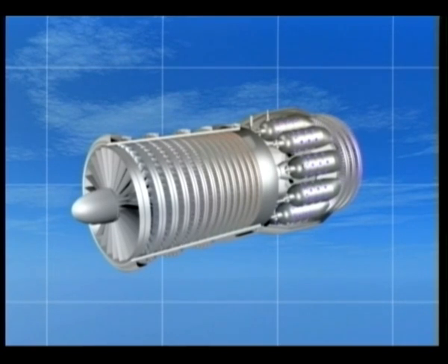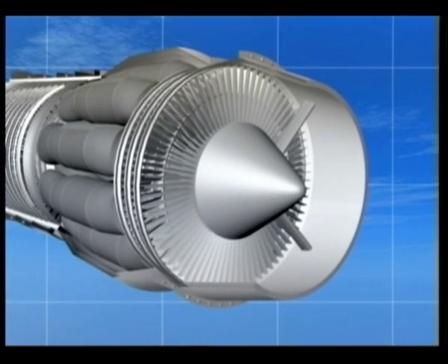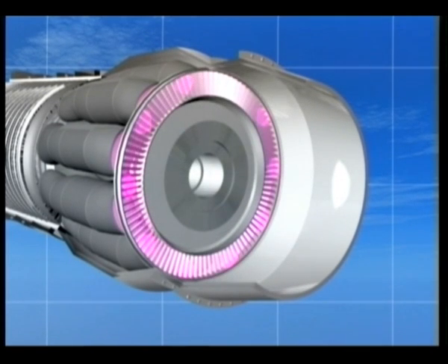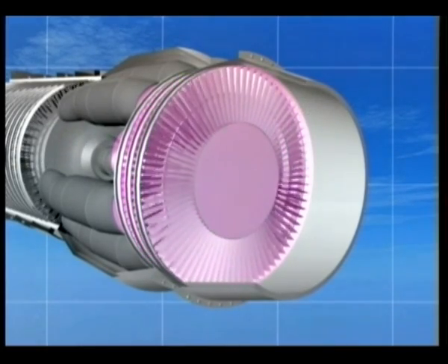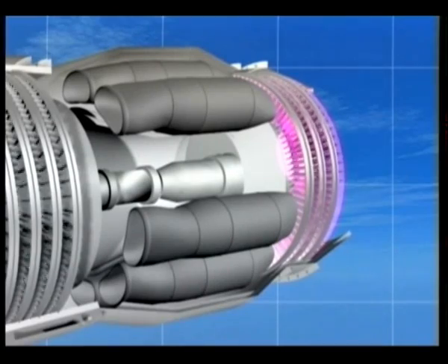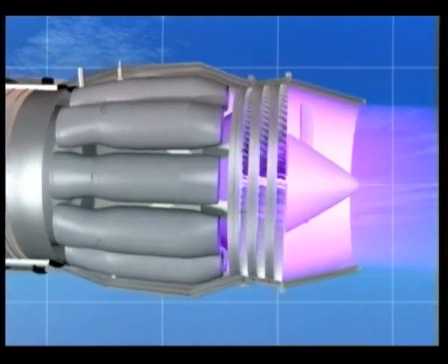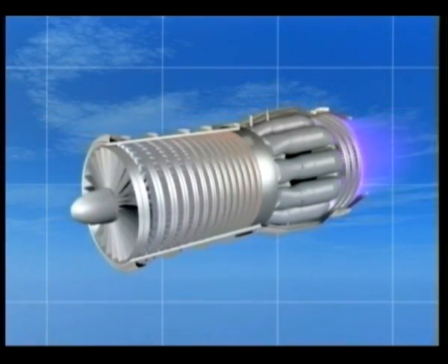the turbine. For a continuous flow process, if the flow is led through a convergent passage, the velocity must increase and there will be a drop in static pressure, density and temperature. This is the expansion process. The turbine disc carries the turbine blades and transfers their rotational force to the turbine shaft. They must withstand high temperatures and the very high centrifugal forces of the turbine blades. They are air-cooled.